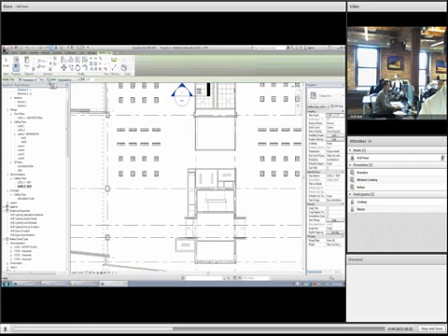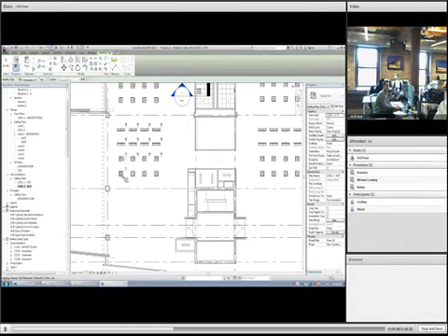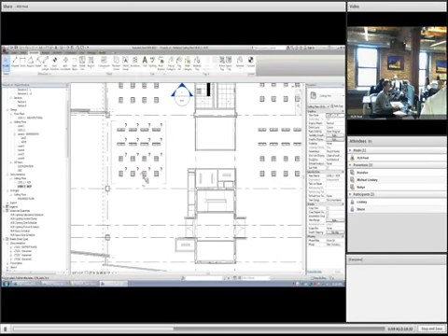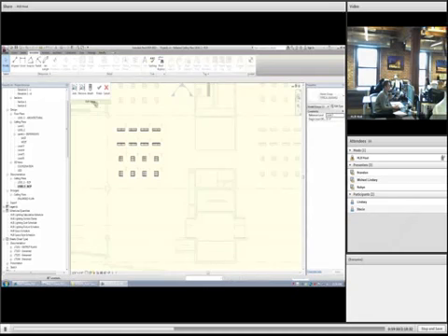I'm going to make sure that I don't have the leaders on. Go here and tag each one of these individually, just for this group. A little bit of repetition here, which is okay. Click on that group. Notice the tags are not part of that group. Hit Edit Group, and then I can hit Add.